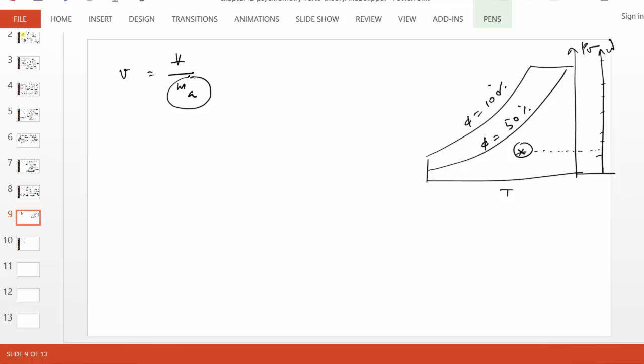Why is that? Because if we went by the traditional thermodynamic definition of specific volume, the mass of moist air would include the vapor mass. But the vapor mass is a variable. Suppose in your room you have 1,000 kg of air, and maybe a few kg of that is water vapor. That number can change, whereas the dry air amount usually doesn't change much.